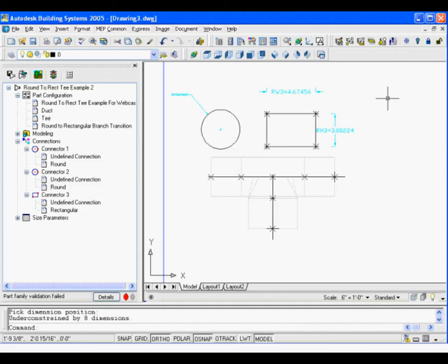These are actually probably more efficient than a block-based part, because behind the scenes of Autodesk Building Systems, these parts, remember we said they're a unique object type. That object type has been developed inside Building Systems to be a very efficient type of object, parametric objects. Think of AutoCAD: the more blocks you put into a drawing, generally your drawings get large.